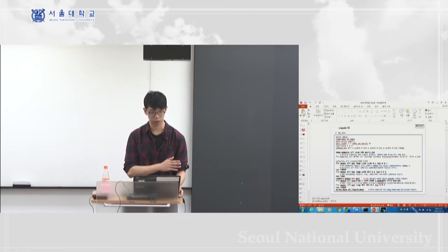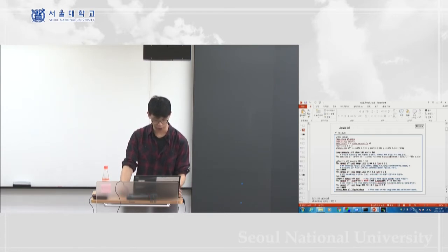As we already mentioned last lecture, we can use a very high temperature to start with, and it's okay because it's gonna equilibrate very quickly. And then we're gonna do this NPT simulation with a superheated temperature of 1200 Kelvin.